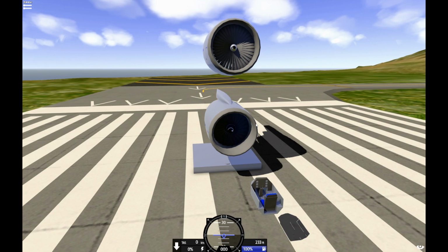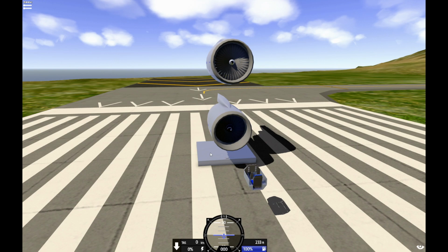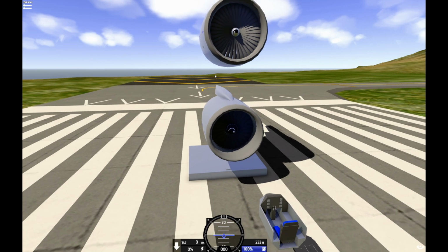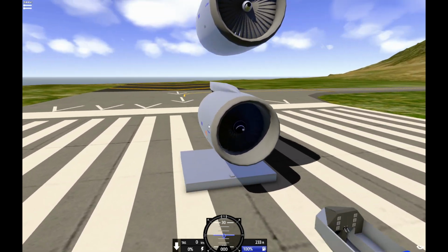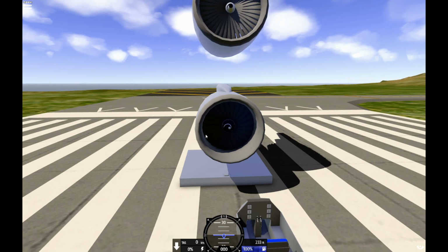I want this engine to be realistic in that you don't just click a button and it turns on, or you don't just turn it on with throttle. For example, the game's basic engines, you control them just with throttle by default. So they're apparently idle even though they're actually not spinning. And then when you apply throttle, they just instantly turn on. I want to have to apply pneumatic air to start the engine, or a way to spin it up. When N2 is above a certain percentage, then I can input fuel and then the engine will start.